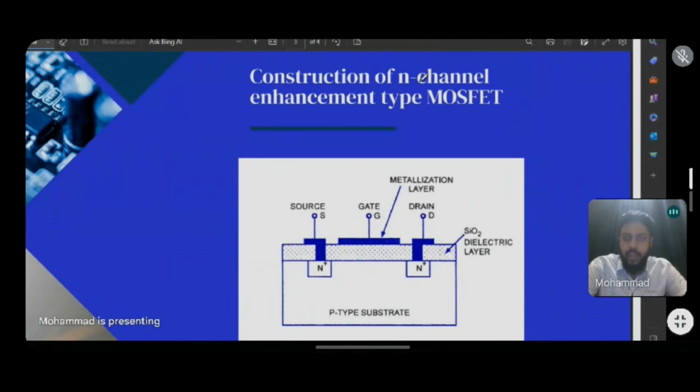So for the N-channel enhancement type, we have a p-type substrate, and then we need two N wells, as given over here, obviously with a depletion layer. With the two wells, we have two terminals connected via a metal contact. One is the source terminal and another is the drain terminal.